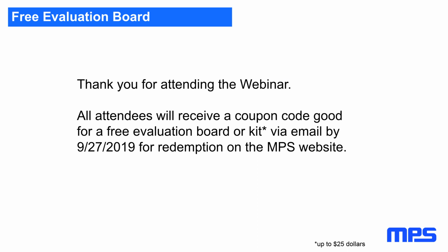How about long aspect ratio ceramic capacitors, for example 0612 and 1206? Do they help with high frequency harmonics? Yeah, the idea of these odd-shaped capacitors is to make the parasitic inductance smaller, and they work in that manner, as the parasitic inductance gets smaller as long as the shortest magnetic path is around these capacitors.